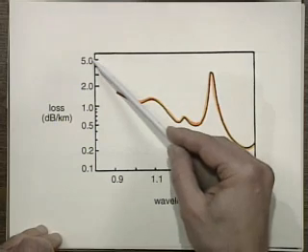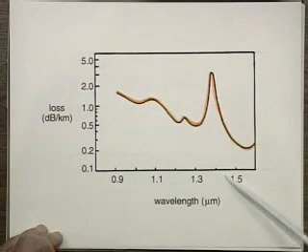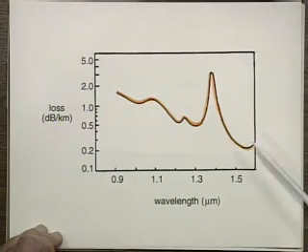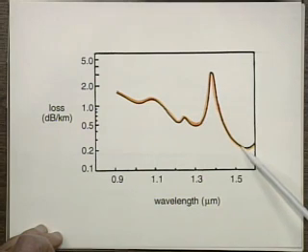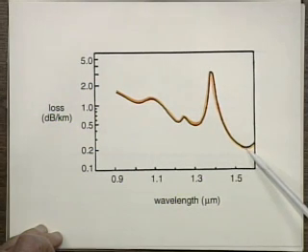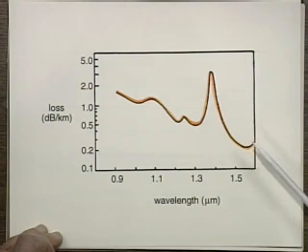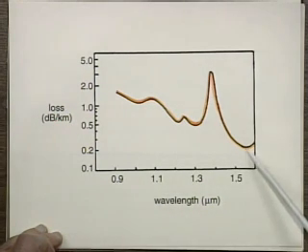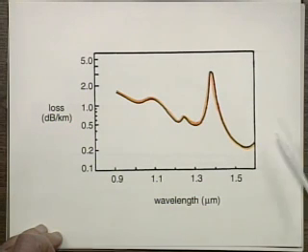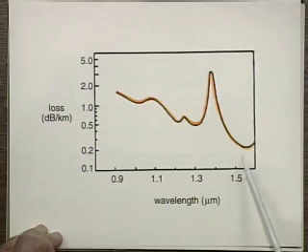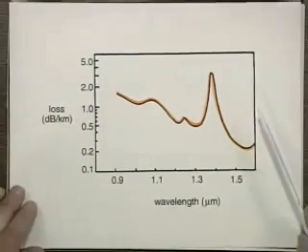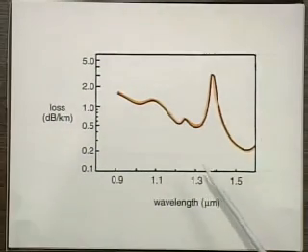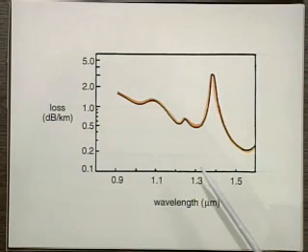So you're boxed in on one side by Rayleigh scattering. The other side, going up, is the material absorption, and that's why you have the lowest loss around here. And that's about the best you can do. If you want to reduce this loss from, let's say, 0.1 or 0.2 dB per kilometer, then you have to use other materials, materials whose material absorption is further into the infrared. So I'm afraid we're not going to get into the visible and have low loss because of the Rayleigh scattering.